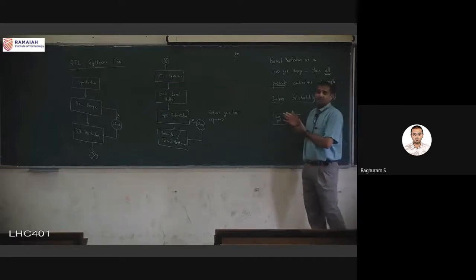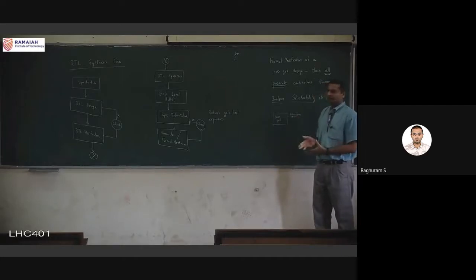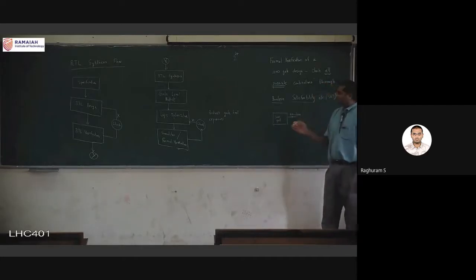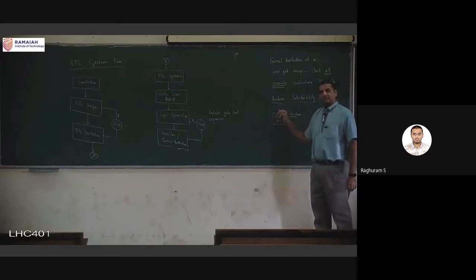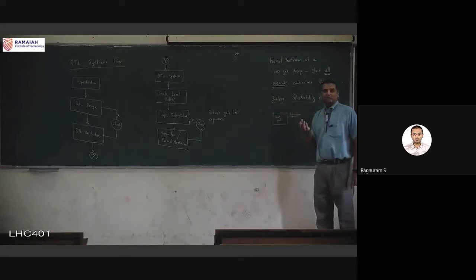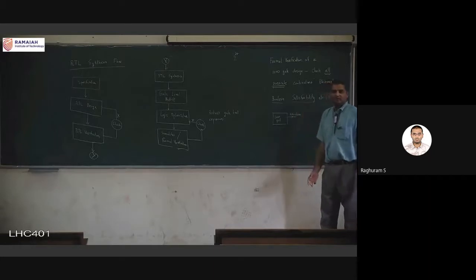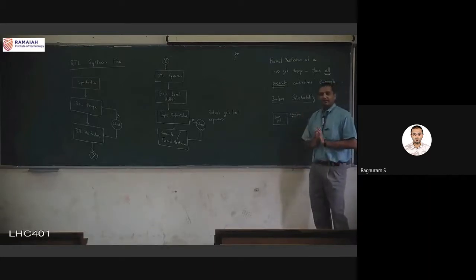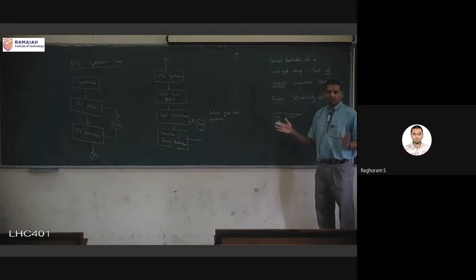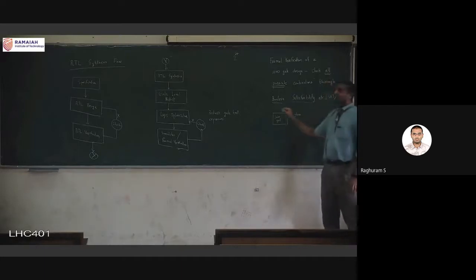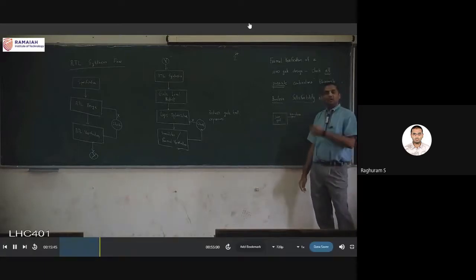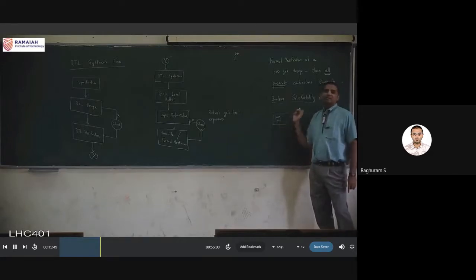We can ask questions like this to the solver, and this only works with Boolean because the 1000 gates' inputs and outputs can have only 2 values. If you have 25 gates, for example, you can sit for maybe 1 week and work out all the possible combinations. That would be simulation. Formal verification uses completely different algorithms, mainly Boolean satisfiability. Based on these algorithms, without doing a simulation, it can verify statements like these for us.